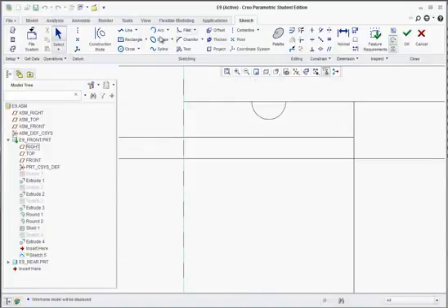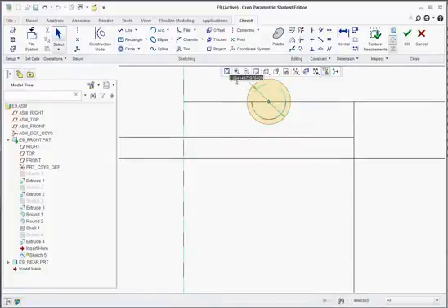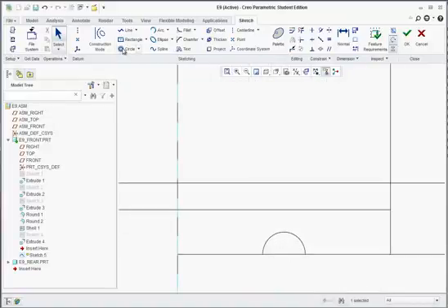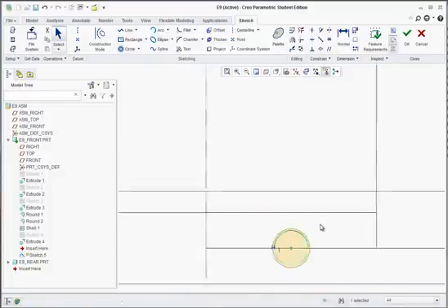So for this, we could go to the circle tool or offset, even, go to concentric, select that edge and drag out a little circle, a little bit bigger than the last one. We want a little bit of clearance, so it was 0.5 originally, so why don't we do 0.55, so it's a little bit larger. And we could just go down here and do the same thing. Make sure concentric circle is selected, select that edge. We should be able to find R, which is equal to that other end. And then middle click a couple times.